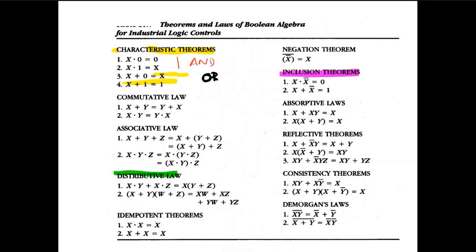So, if it was 50 or 60 hertz for those older PLCs, very long programs as it scans from top to bottom have some issues. The issues are, yes, it will scan. It is likely when it starts scanning the first line, and let's say you have 1,000 lines in your code, and then at the 894th line, conditions were right, and the output became true. But the PLC is starting to scan from the top. By the time it hits the 894th line, who knows, the condition might have changed and the output might have turned off, which is not good for process control. That's the reason why you should make the programs compact.